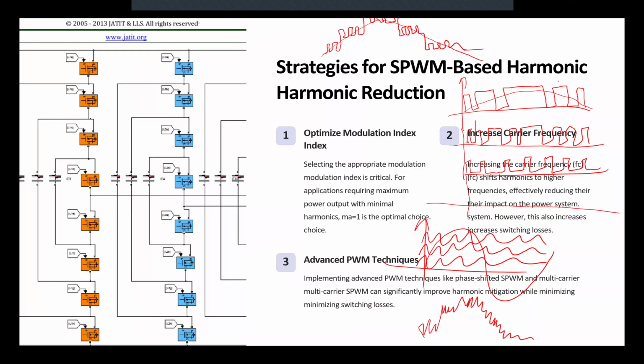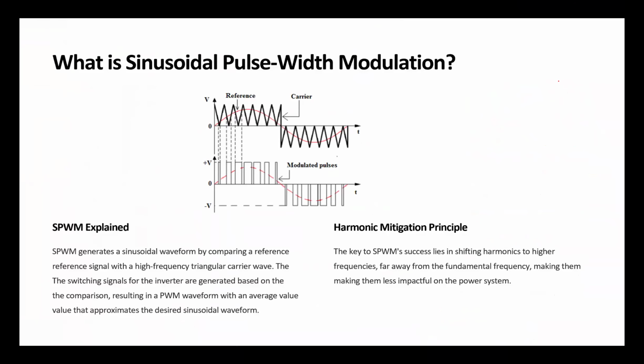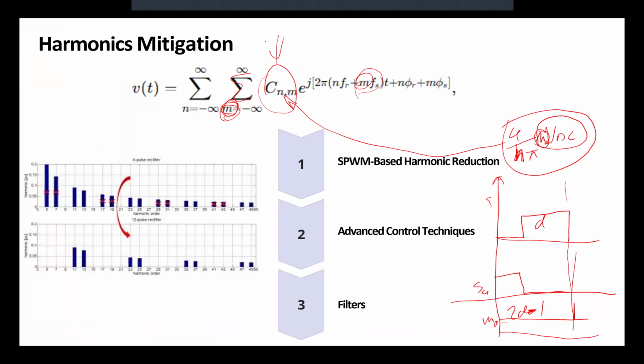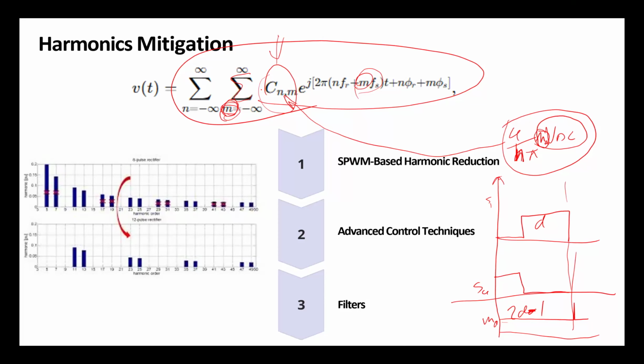Now, the mathematical answer. You have 3 PWMs, each of them has this formula, correct? You are stacking them on top of each other, so in series, so they are adding together. Makes sense? But one has C1, another has C2 amplitude, another one has C3 amplitude, even considering that all of them have the same switching frequency.